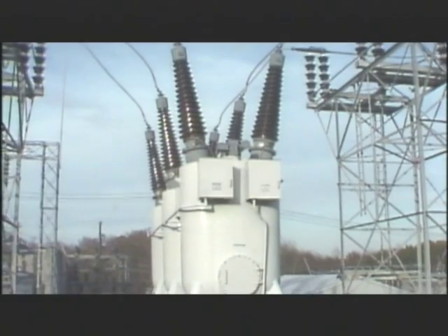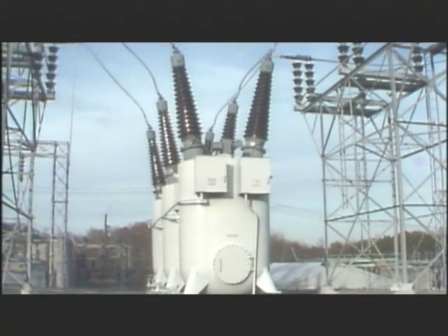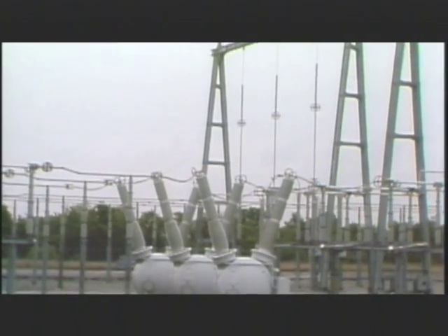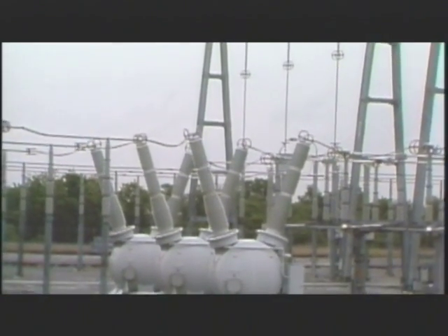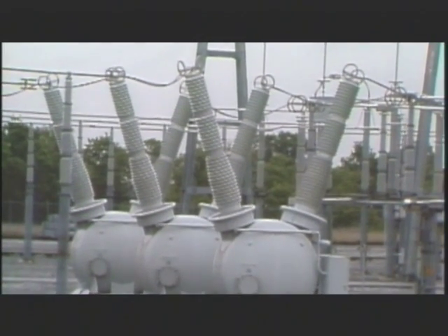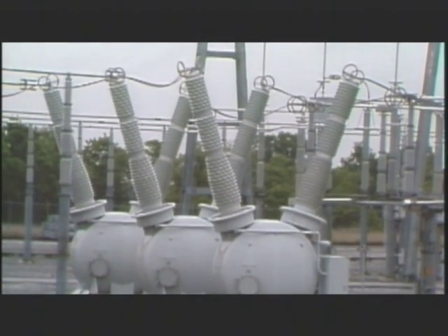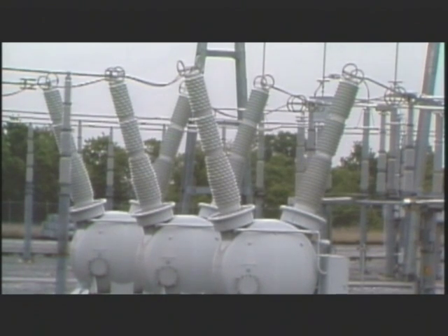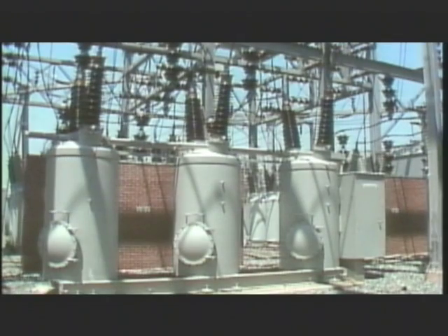and disconnects. Oil circuit breakers, commonly called OCBs, and sulfur hexafluoride or SF6 breakers are different solutions to the same problem. The problem they solve is how to extinguish an arc, the electrical spark that results from opening and closing a circuit. The oil circuit breakers found in switchyards are usually housed in large tanks like these.